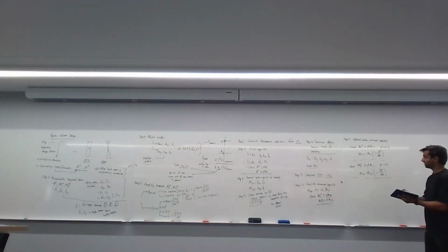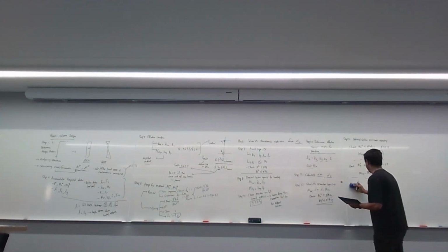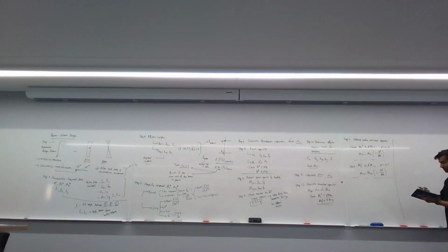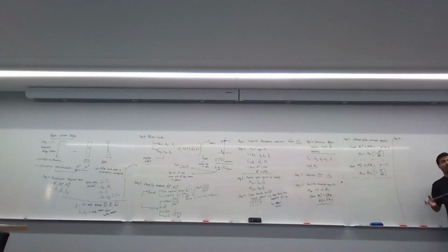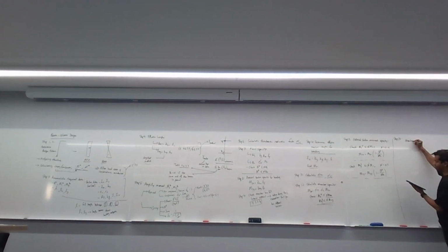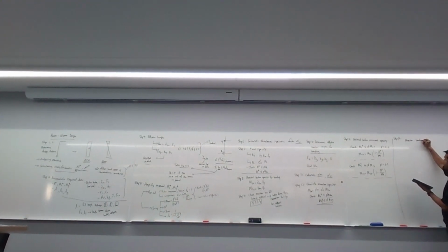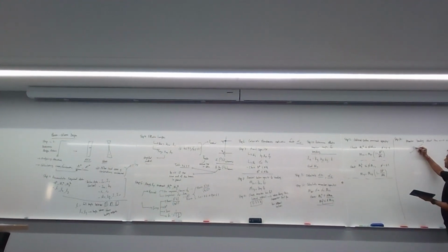Now finally the last step, step 14. I'll write step 14 on this side because it's slightly long. Step 14 is, now you've got to do one last combined check, okay? To do this combined check, there's a bit of a flow chart that I've used that I find easier to understand. So you ask yourself, is the member bending about the x-x axis? Okay, you ask yourself that question.